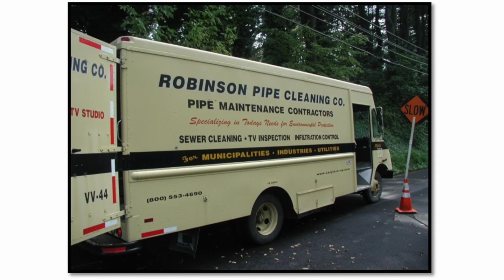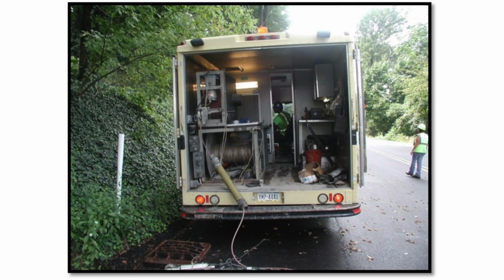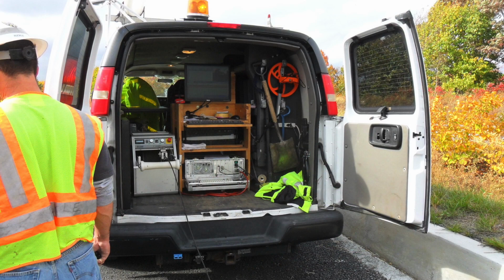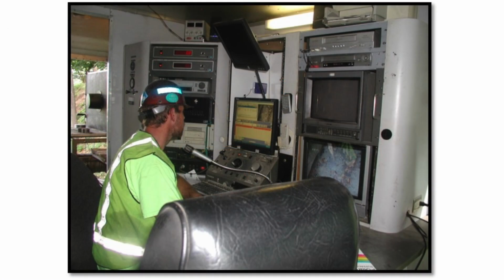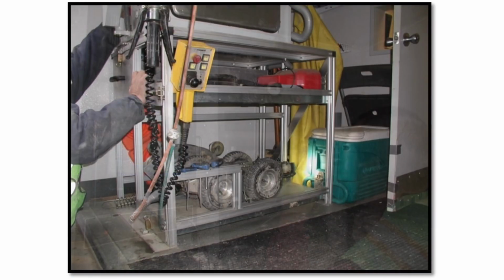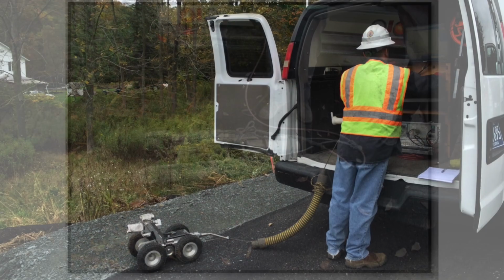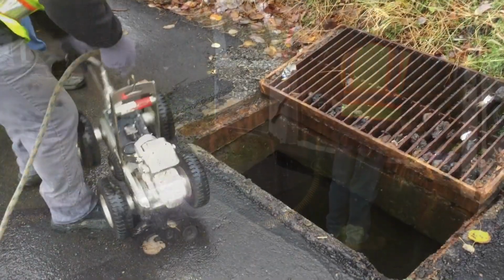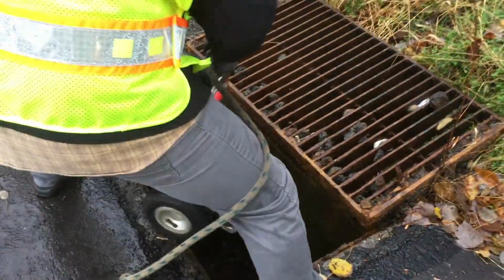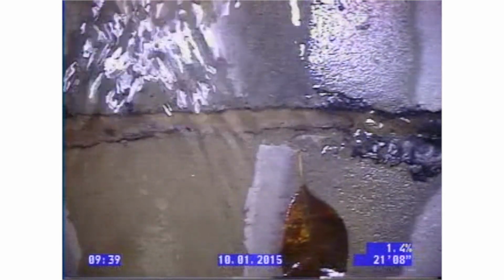When using the crawler-mounted camera with laser profiler, there are many pieces of equipment that are used to complete the inspection. The rover, computer system, power source, and other essential equipment is usually contained inside a vehicle. The operator controls the rover by remote with the equipment in the vehicle. The entire operation is controlled from the console area. The operator sets up the rover and laser equipment and preps the rover for operation. Once set up, the rover is placed in the pipe or inlet, and the video assessment of pipe condition begins. The video is recorded, and any required items are documented for the pipe run.